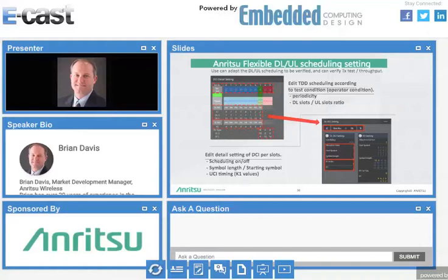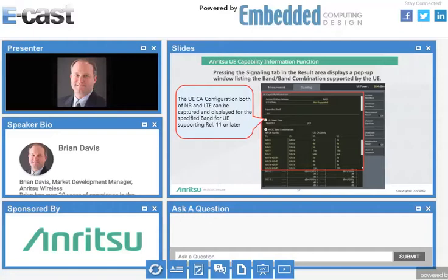So, if there's a lot of downlink streaming going on, there's going to be more downlink slot numbers. If there's a lot of people uploading video, then there'll be a lot of uplink slots. So you can vary the DCI formats, the time slots, et cetera, in TDD. And again, you can do this on the fly too when you're in a call.